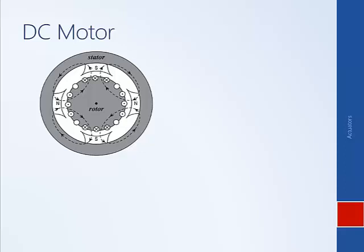So in the previous example, we basically only had two magnets, a magnet with a north pole pointing towards the center of the motor, and a magnet with its south pole pointing towards the middle of the motor. This DC motor is what we call a four-pole motor because it has four magnets. It has two magnets with their north pole pointing towards the middle and two magnets with their south pole pointing towards the middle. And these four magnets interact to create these magnetic fields shown by these dashed lines.